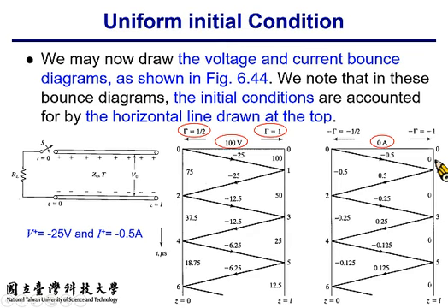Okay? So the total voltage observed on the right end initially is 100 volts before seeing the V plus signal. After that, it becomes 50 volts because there is 100 minus 25 minus 25, so it's 50. And the minus 25 signal will go to the left end at t equals 2 microseconds. And because the transmission coefficient is minus 1/2, part of the signal gets reflected and part of the energy is dumped into the resistor continuously.